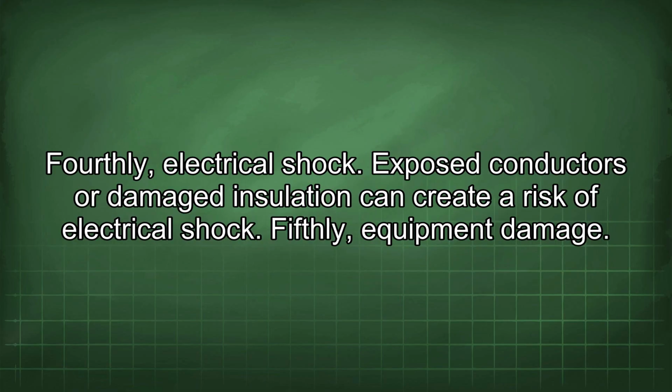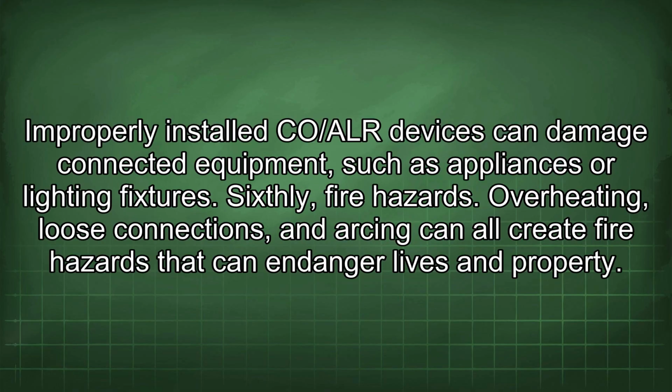Fourthly, electrical shock. Exposed conductors or damaged insulation can create a risk of electrical shock. Fifthly, equipment damage. Improperly installed CO/ALR devices can damage connected equipment, such as appliances or lighting fixtures. Sixthly, fire hazards. Overheating, loose connections, and arcing can all create fire hazards that can endanger lives and property.